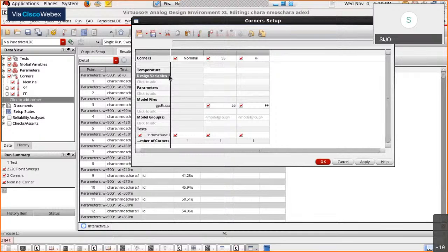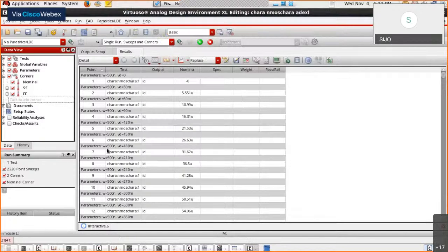So in terms of design variable, you can actually specify the supply voltage there, and you can also run for a supply voltage variation. So this is how you set up the corner. I'm not going for temperature variations here because it will take huge time. So you can click OK. We'll run it for the corners at least to get an idea about the flow, how to set up.